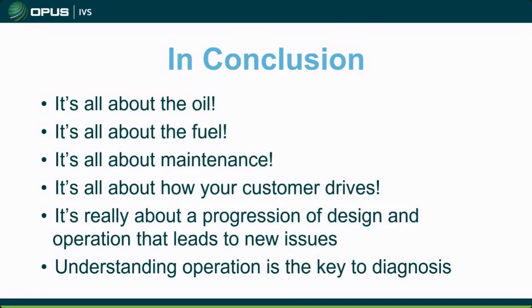And if you're not really getting up to that, you're doing a lot of short trip driving, then you're never going to get these systems hot enough to get that good oil air separation. And you're going to end up burning a lot of oil. You're going to end up with a lot of carbon deposits, and you're going to have issues.